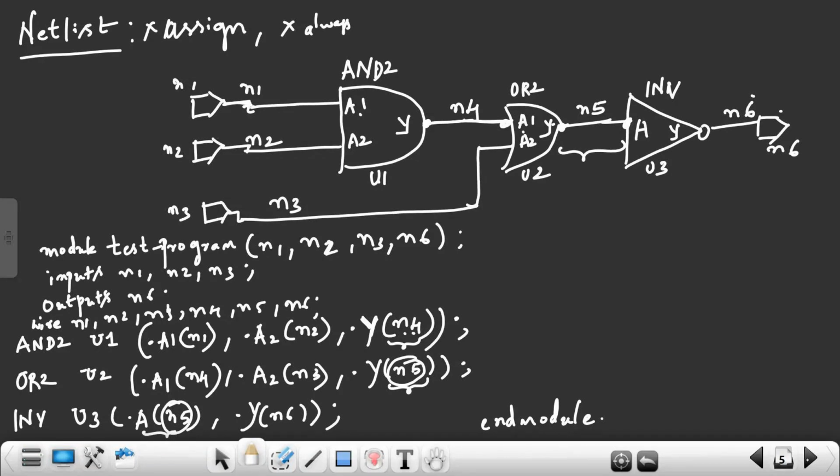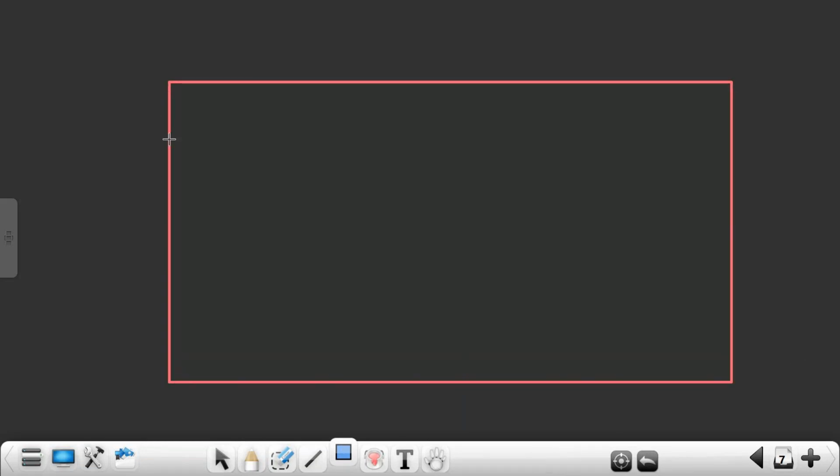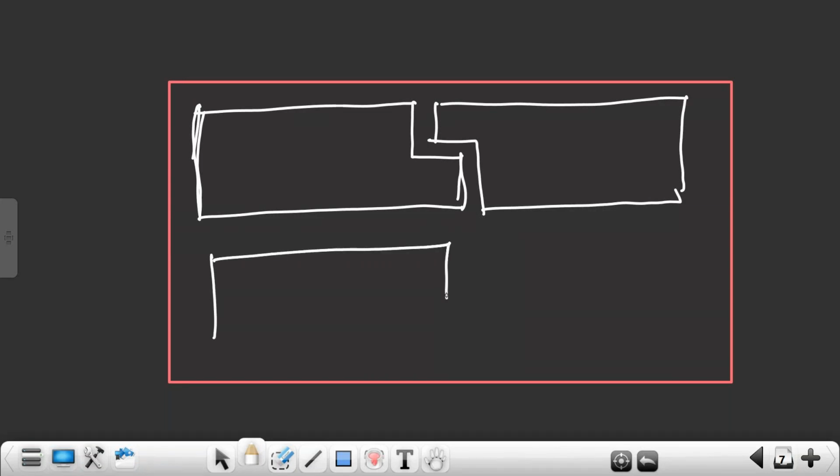So what will my chip designer do? The top level designer for the physical design will take the entire chip. First he will estimate the chip requirement and the area requirement, and he will divide it into functional blocks like this. Okay, this is one functional block. The entire chip you divide based on the area and based on the modules. You divide the chip like this into blocks.